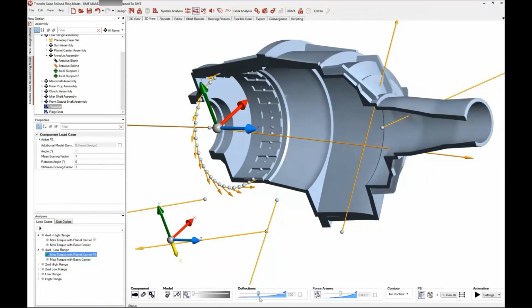And just to reiterate, this allows us to specify various clearances in the spline. So if you have clearances that you want to include in there, you want to be able to simulate those clearances being taken up, loading on every individual tooth, this is the perfect functionality for you. So of course the functionality is a little bit more difficult to use than your standard thing in MASTA. But hopefully this demonstration has kind of shown you that it's not too difficult to set up. Especially if you have this video guide as a backdrop, you should be able to do the functionality and perform the addition fairly easily.